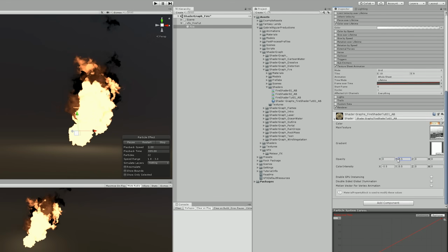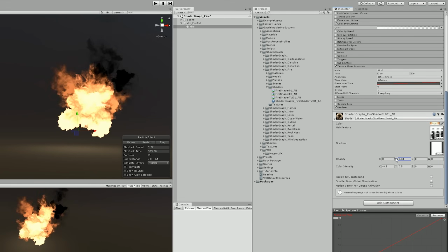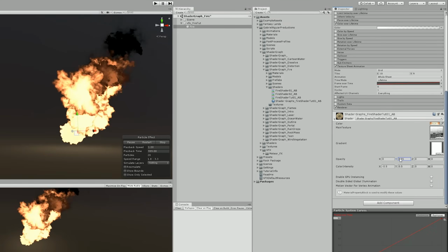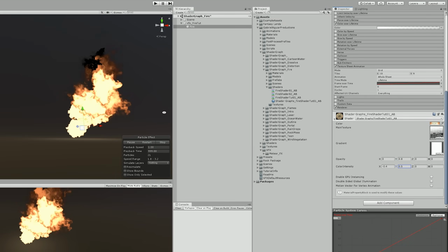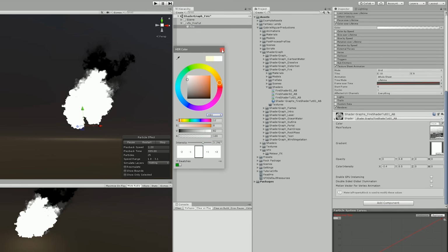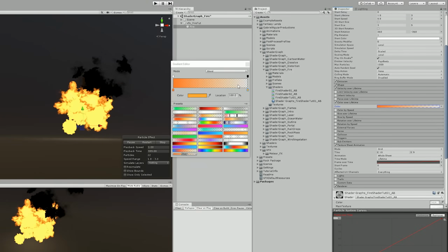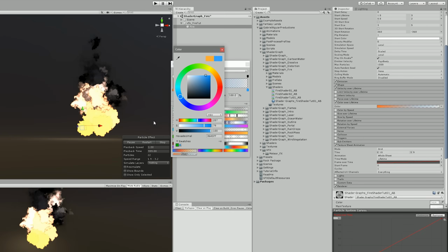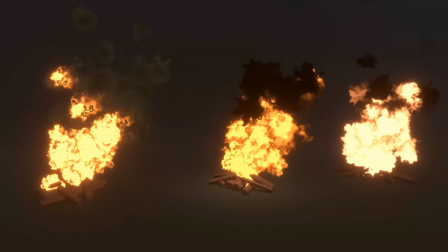And you may also want to play with the Y values of the opacity. It will let you control how much smoke there is. Of course, there is a limit, obviously. And that's quite interesting also. And you can also have the color controlled by the particle system too. You can just set the color of the shader to white, leave the intensity as you want, and in the color of a lifetime we can choose a gradient similar to this one, or you can play around and get pretty interesting results too. There's also much more options like this. Anyway, it's up to you guys.